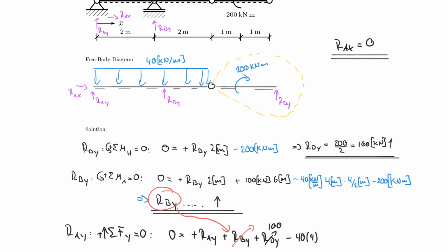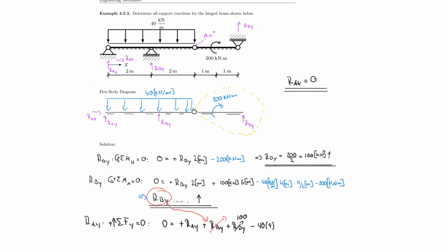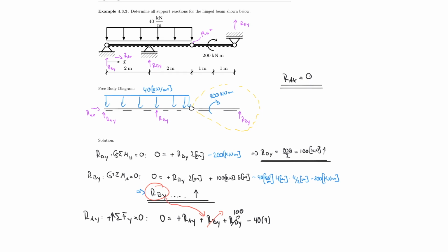And then I could solve this and I would have found all my numbers for this simply supported compound structure, if you will, or a statically determinate compound structure. And so you know now how to interact with these hinges here and how to calculate support reactions if there's a hinge in the system that connects a system on the left side to a system on the right side. So I believe that is everything you need to know to successfully complete your homework and to move forward in this class. So let's conclude the lecture on our last page and let's talk about the description of the homework.